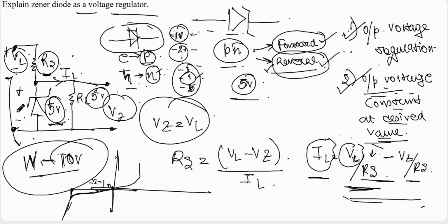So if we fix the DC supply at 3 volt, then we will get 3 volt at the output. It will be of no issue. But suppose we put 8 volt at the input, then the zener diode will produce 5 volt at the output. It will not produce 8 volt, because after 5 volt the current will increase exponentially and it will attain the breakdown region.